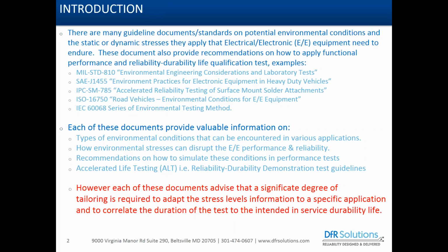However, they're not complete documents. Each of them advises that a significant degree of tailoring is required to adapt the stress level information to a specific application, and then to correlate the duration of the test to the intended service durability life of whatever product or system you're working with.